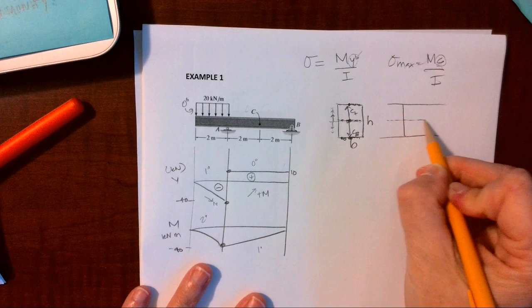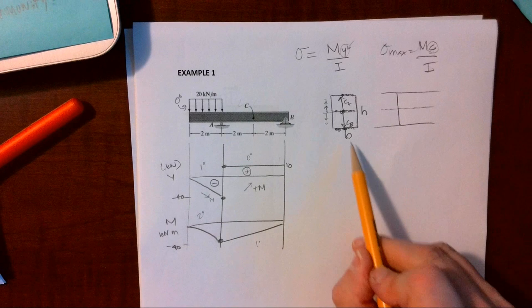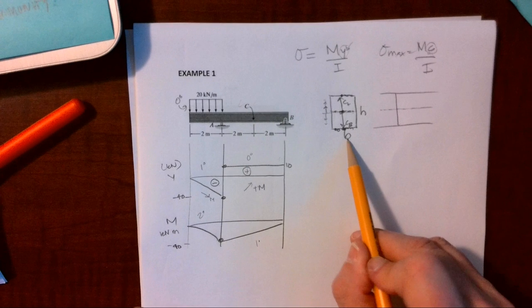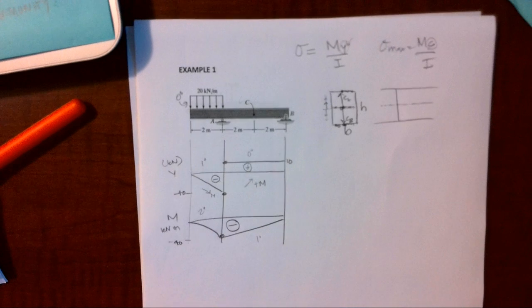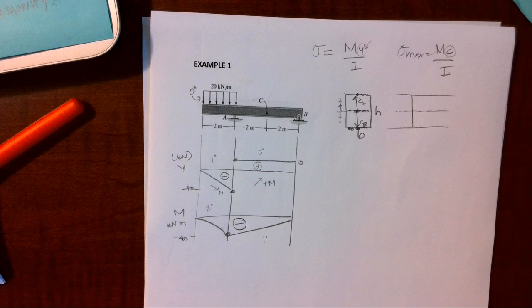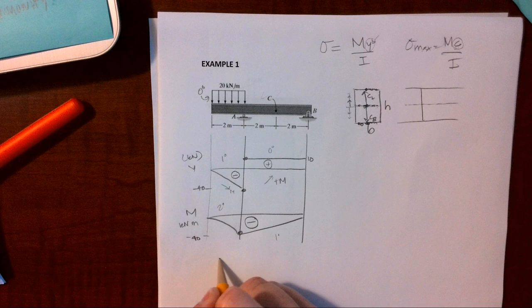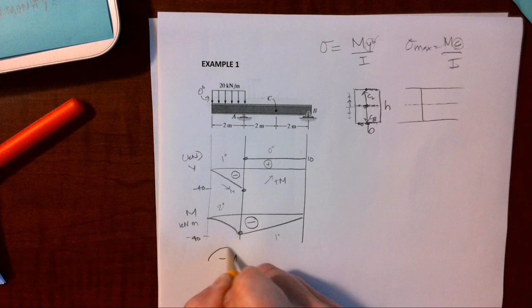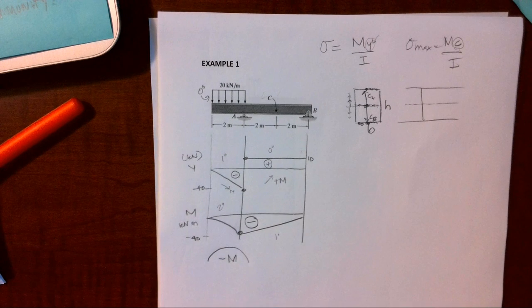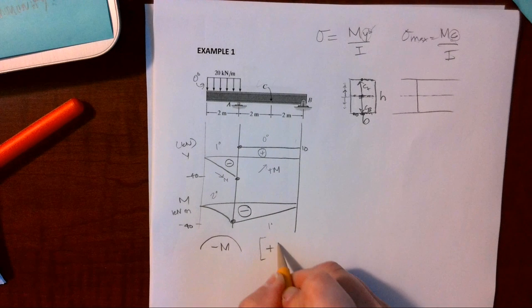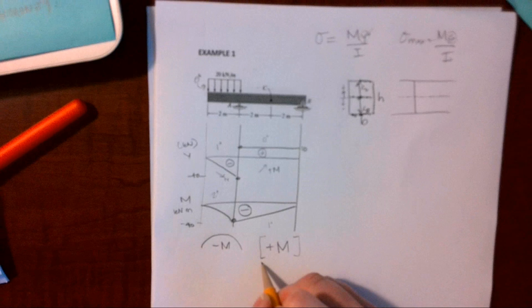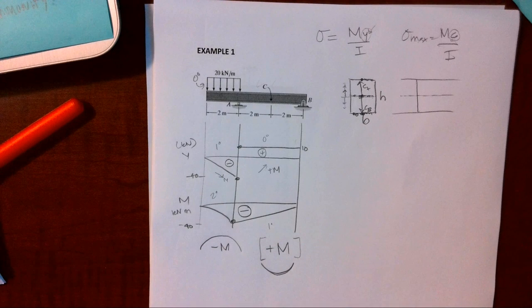So again, you need to kind of understand why the equation looks the way that it does. If this is my cross section, base times height, I can go over here and see I have a negative moment. This is where you need to remember behavior. A negative moment means the curvature of my beam looks like a rainbow or unhappy face. If I were to have positive moment, which we don't on this page, I need to remember positive moment gives curvature of the beam that looks like a smiley face.